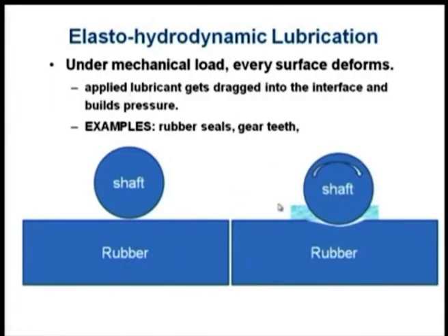If there is a deformation and we pour the lubricant, because of the rotation, the lubricant will be brought into this kind of interface, which can retain the lubricant for some time compared to a straight surface. It is making a shape in such a manner that it can act as a reservoir for the lubricant. That is helping us. The deformation and the subsequent viscosity increase both act together and give us a very favorable environment for the tribo interface, where the friction will not go to a very high value because there is a change in the film thickness itself.